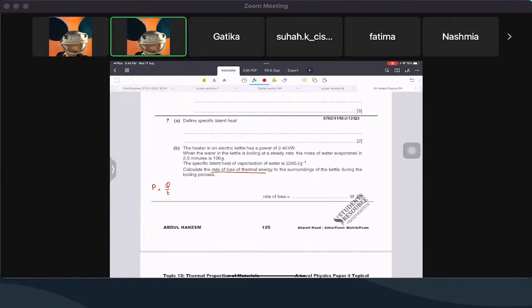First of all, we have the mass, right? We already know this is boiling, so Q will be equal to L_v times m. Do you guys agree? So the latent heat of vaporization is 2260, and the mass is also in grams, so I'm just gonna multiply this.